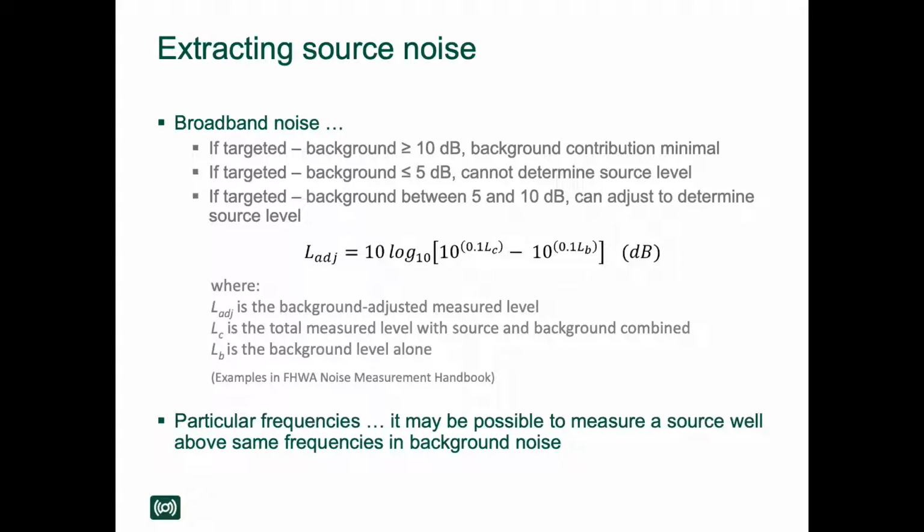Now, if you're interested in particular frequencies and not just background noise, it may be possible to extract the source if it's well above the same frequencies in the background noise, even if the broadband sound level is within 5 dB.